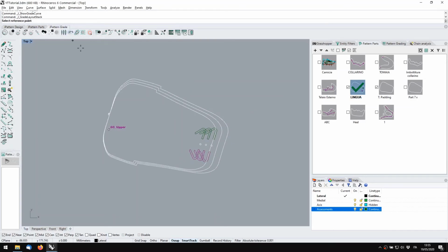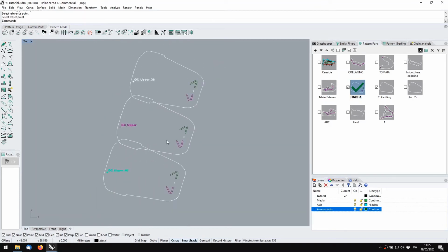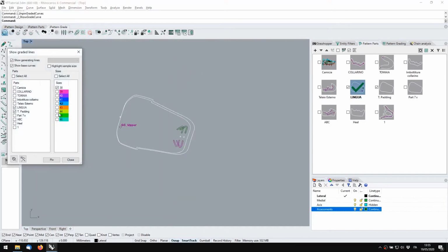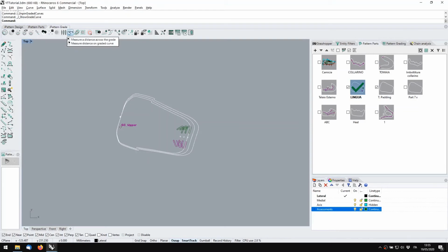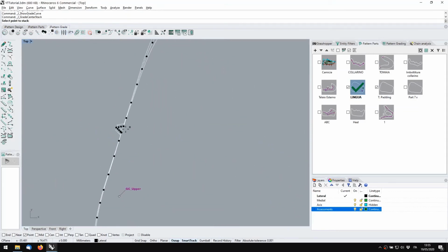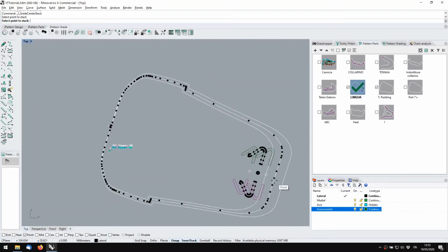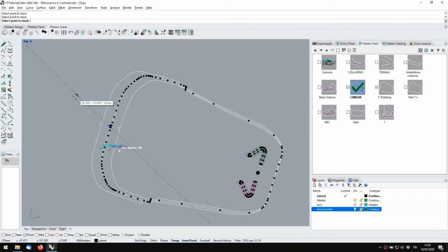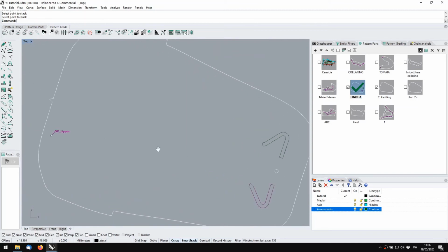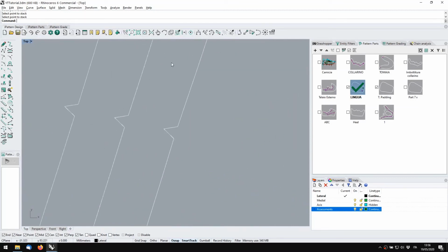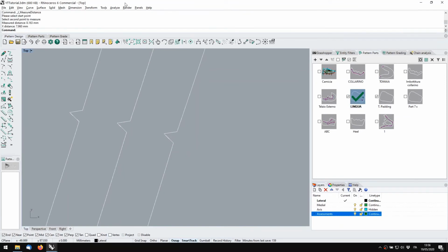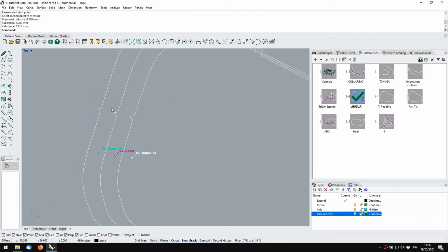You can layout them if you wish to make any measurements. You can, of course, stack, which is more interesting. So place the graded sizes on a specific point, so that you can compare them in various positions. So for example, I want it like this. And now I know that they're all on this place, and I can, for example, take my measurement here and say, okay, this is 8.163. This is 8.28, for example.